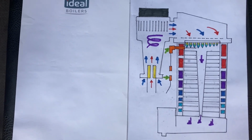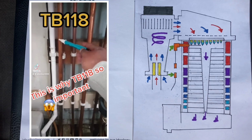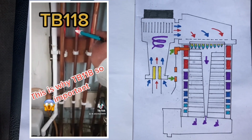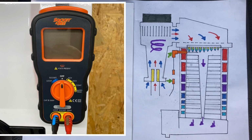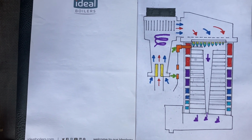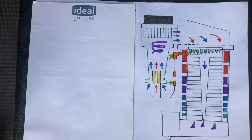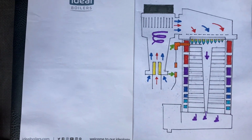So I did the electronics tests, I think they call them TB118 these days, just to make sure there were no wiring issues. There weren't. I always start from the basics. I did working pressure, and that was fine. Then because it was a hot water temperature issue, I went down the route of looking at the thermistors and the wiring harnesses, and they were fine.